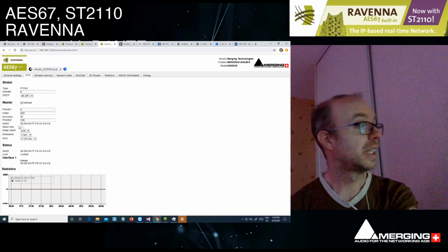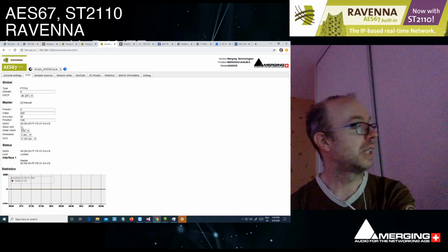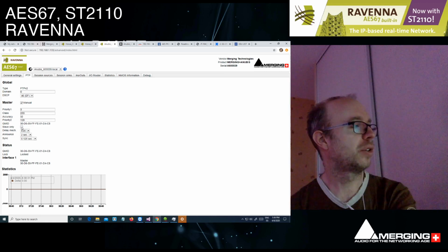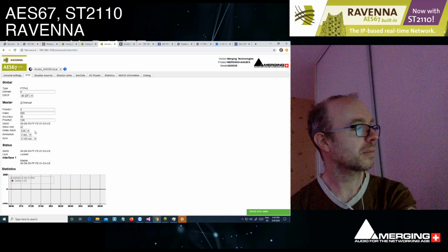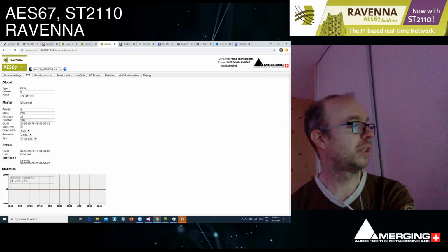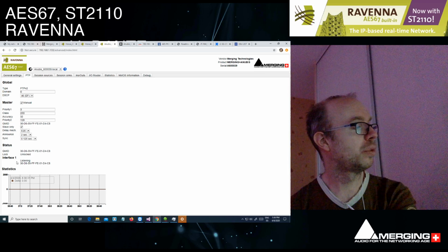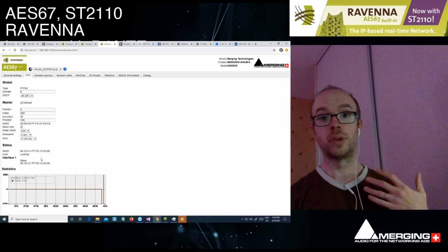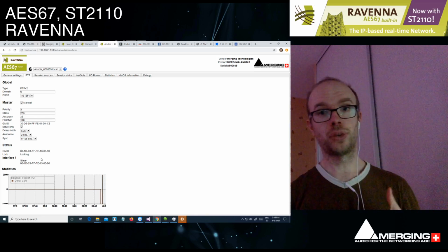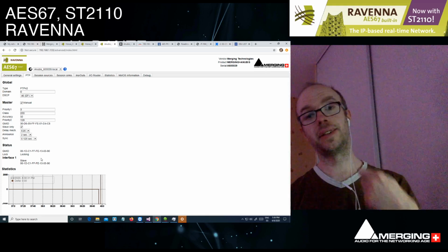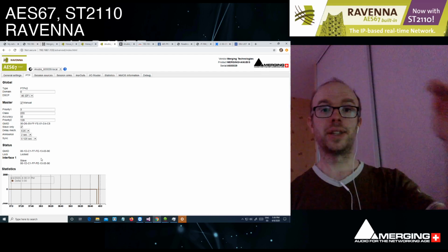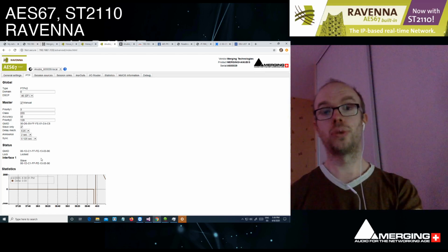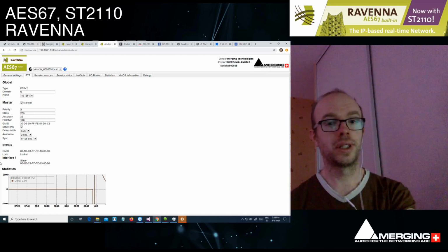So this checkbox, for instance, is really useful, and it's a checkbox that is used to constrain the device to be only slave in terms of PTP. So if I check that, the device will lose its master status and will begin to be listening. And a listening device is a device that is waiting for announces from the masters. So when the master disappears from the network, every device that feels like it should be the master is sending a packet, an announce, with its different parameters, and the device with the best parameters wins, and all the devices do sync to that.